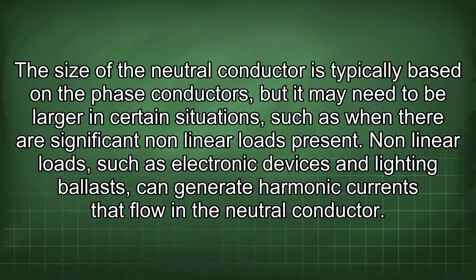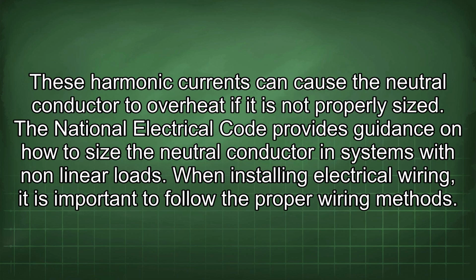Nonlinear loads, such as electronic devices and lighting ballast, can generate harmonic currents that flow in the neutral conductor. These harmonic currents can cause the neutral conductor to overheat if it is not properly sized. The National Electrical Code provides guidance on how to size the neutral conductor in systems with nonlinear loads.